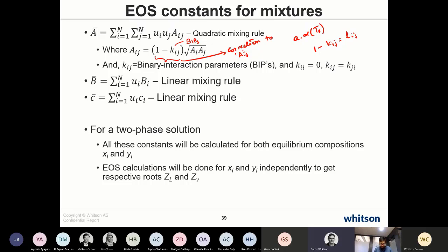So you actually determine the alpha term or the m or the acentric factor in order that the equation of state predicts the normal boiling point of a known C7 plus fraction. So that's how we control the vapor pressure curve part: knowing one point on the vapor pressure curve, namely the normal boiling point. Okay, so yeah, because I was missing that you need to anchor something. Yeah, you anchor it to that. That's how we do it. Okay, that's the most consistent way. Yeah, thank you.